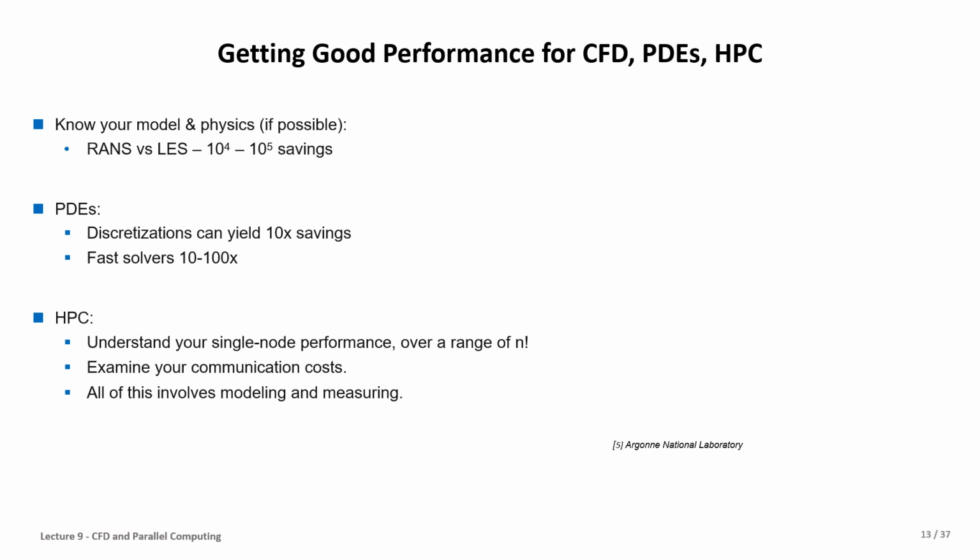If you want a summary of good performance for CFD applications with high performance computing resources, firstly, we need to select between the models for turbulent flow, RANS versus LES, which is also about the cost, how much we can save, as each provides the proper result.